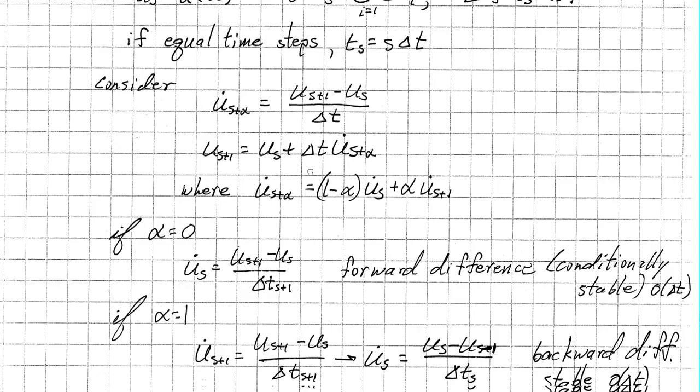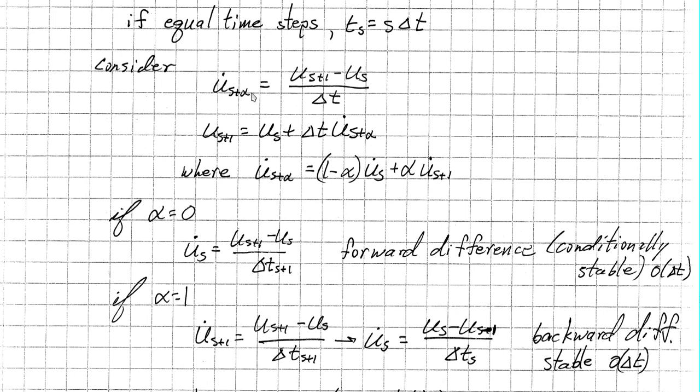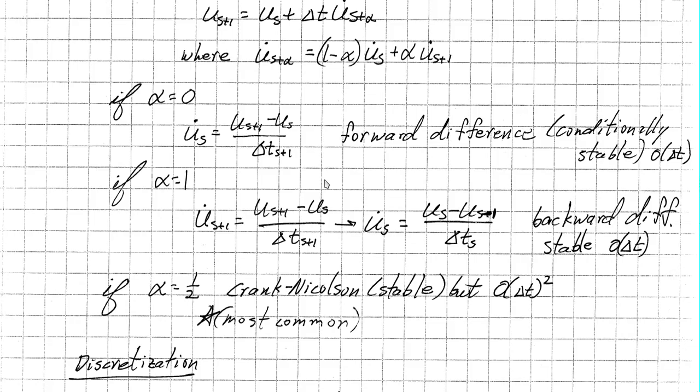Alright, so let's look at the following form. We have this velocity at some incremental time ahead, alpha. We're saying this is the difference over delta t. So we rearrange this. Remember, this is a form of Taylor series. And we're defining this as our velocity as a weight function on alpha. Alright, here's the most important part of this. What do we define as alpha, and how does it impact the solution?